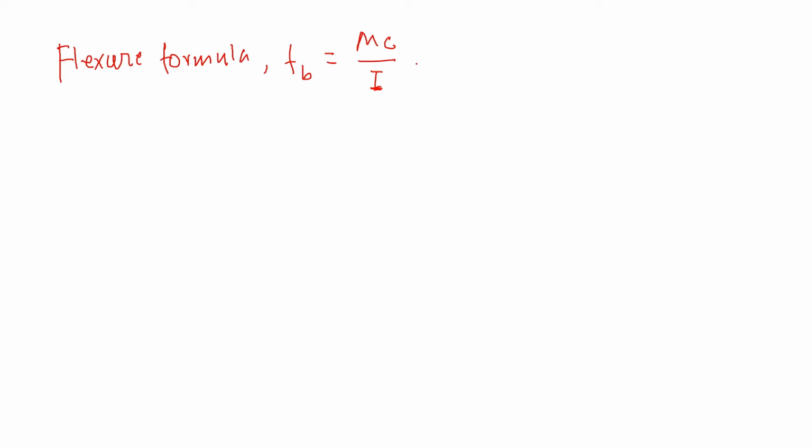We can also express this formula as FB equal M by S, because I by C is equal to the section modulus, the geometric property, which is expressed by capital S. So that's the formula to calculate the bending stress.